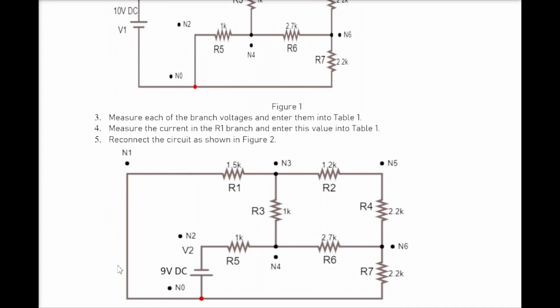Now you might ask a question like, what happens for a current source, right? So it's totally the opposite of what we do for the voltage source. For a voltage source, we short circuit the other voltage sources, right? But when it comes to a current source, we have to keep it an open circuit. If there was a current source over here, say instead of 10 volt DC, then this circuit at this point would have been an open circuit.